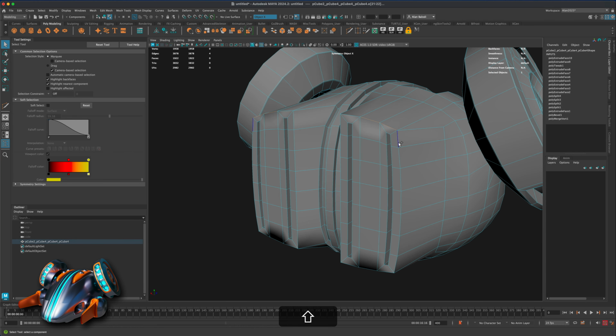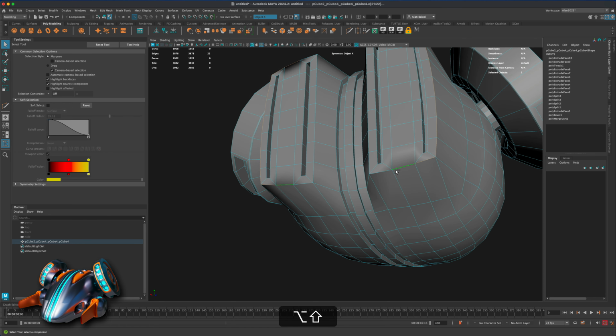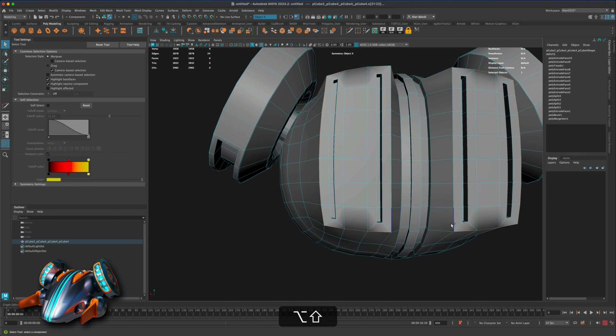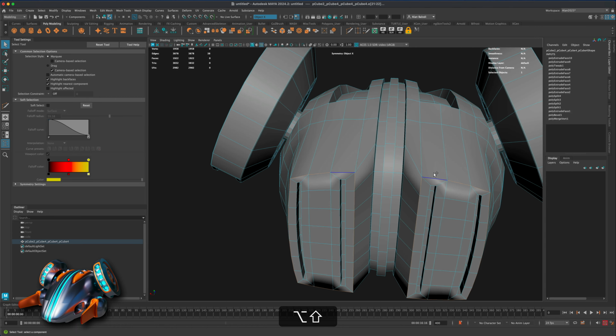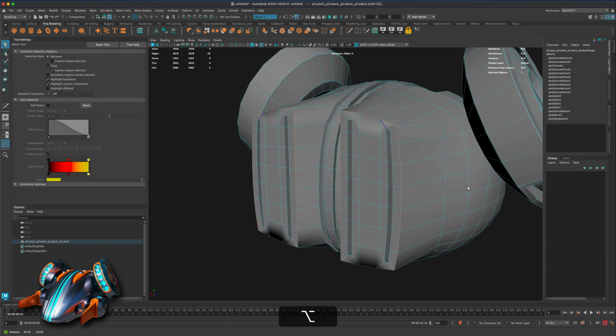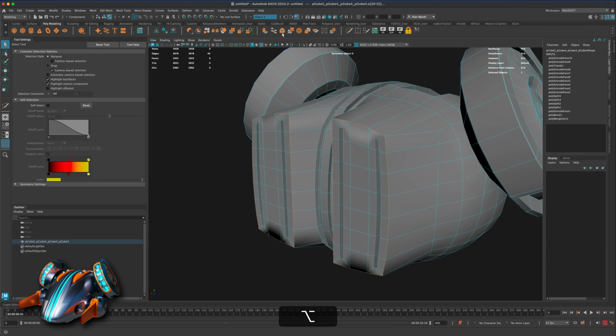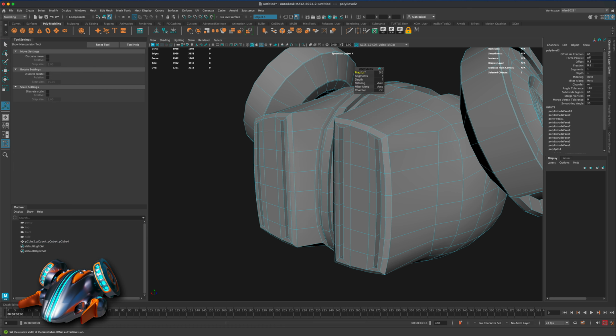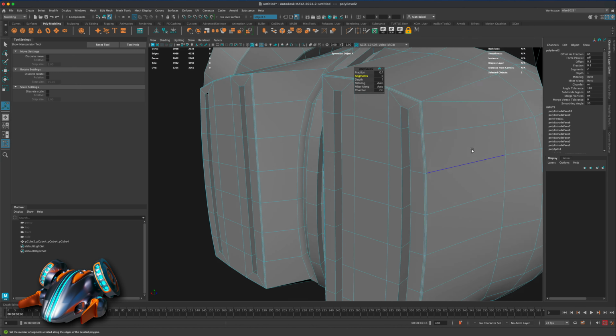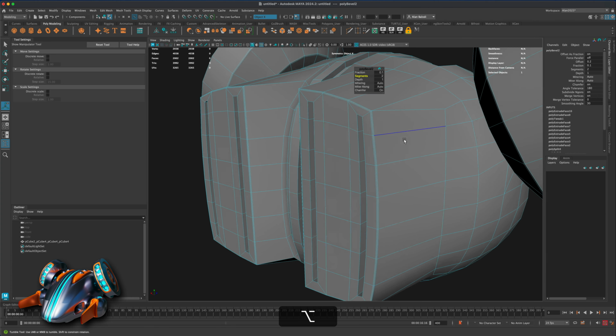Well, I could just simply, holding down the Shift key, go around the whole back like this, come up here, and manually select all of these. And then do my favorite bevel like that. Maybe do something 0.1 with an extra segment inside. And you can see how it's going to hold the shape really nicely, right?